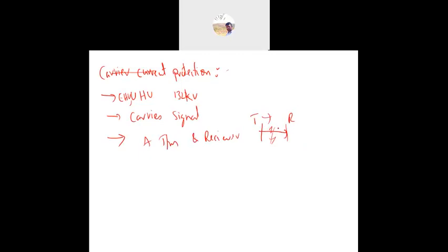The relay is placed at each end within the protected zone. From this, the carrier signal shows where the fault occurs and in which direction the current is flowing, and based upon that the relay will trip. Relays do not trip in case of external faults; the signal dies down. The relays are distance types and their tripping operation is controlled by the carrier.